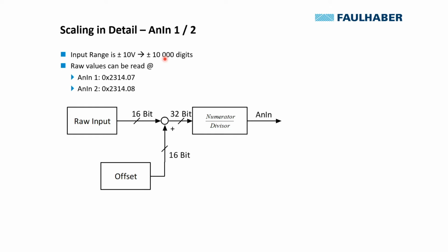These raw values can and have to be rescaled for your applications. Main parameters are the offset and the gain. Additional ones would be the minimum and maximum values and the filter time, but let's stick with the main parameters here and do the scaling.